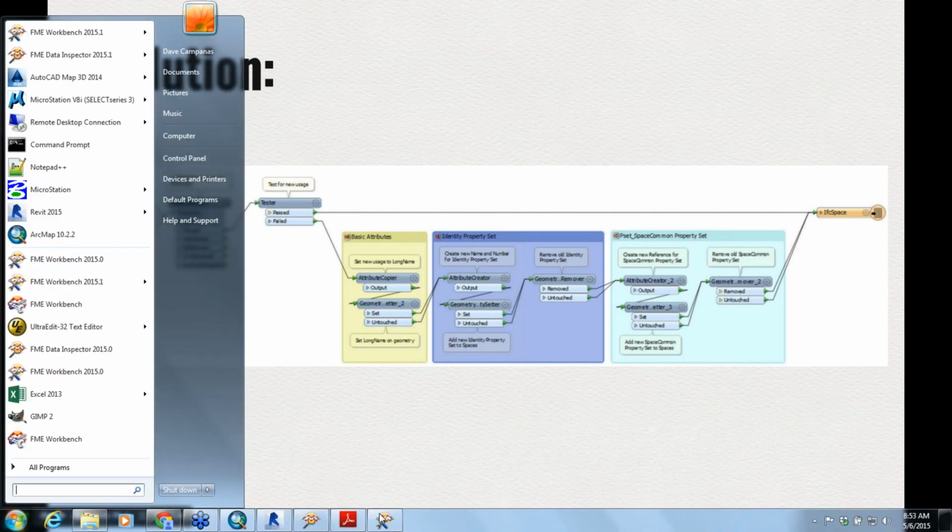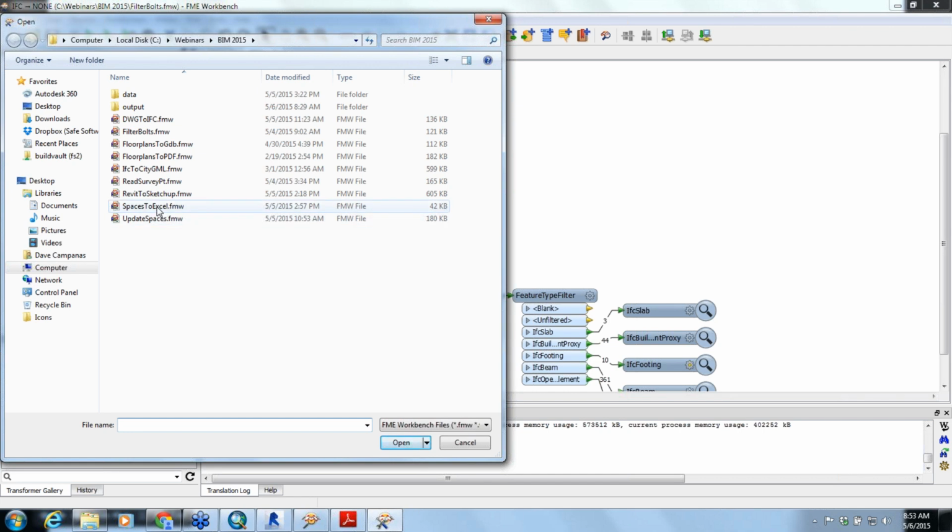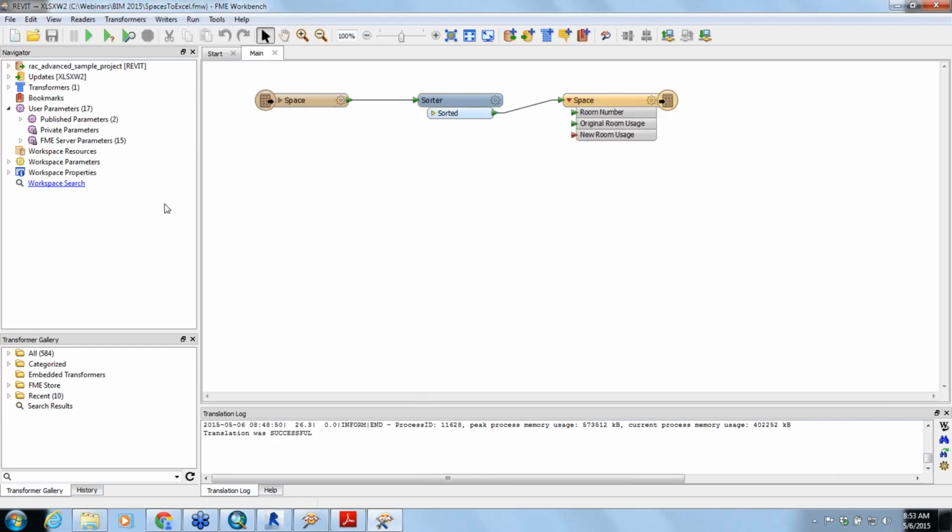You're going to bring her up? I'll bring her up. So again, the concept is let's update an IFC file. Someone actually already asked, can they create an RVZ file and bring it back into Revit? The answer is no, but what you can do is take an IFC file and modify it and create a new IFC file and bring that back into Revit to do some updating, and that's what's going on here.